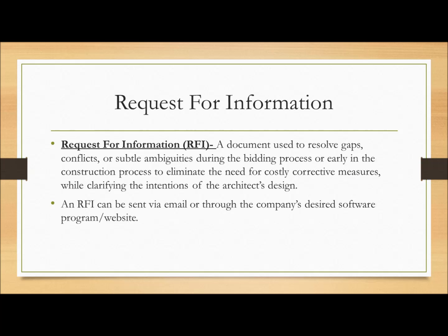A request for information, or RFI, is a document used to resolve gaps, conflicts, or subtle ambiguities during the bidding process or early in the construction process to eliminate the need for costly corrective measures while clarifying the intentions of the architect's design. An RFI can be sent via email or through the company's desired software program or website.